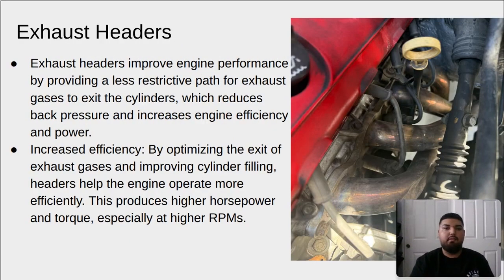Exhaust headers. Exhaust headers improve engine performance by providing a less restrictive path for exhaust gases to exit the cylinders, which reduces back pressure and increases engine efficiency and power. Increased efficiency. By optimizing the exit of exhaust gases and improving cylinder filling, headers help the engine operate more efficiently. This produces higher horsepower and torque, especially at higher RPMs.